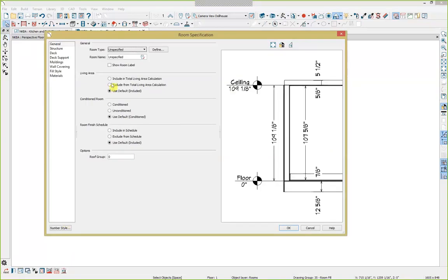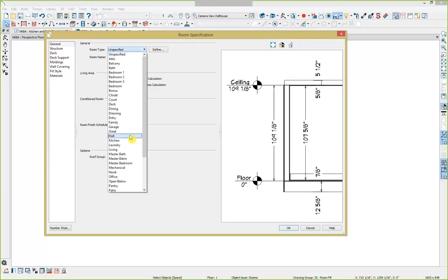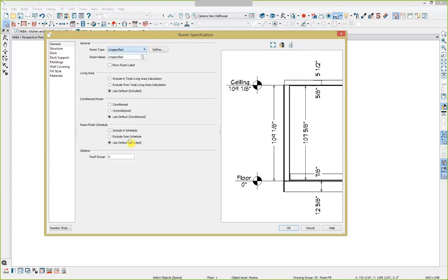And here in the middle of the screen, we open up the room specification, and you can tell the program what type of room type is going to be used here. I'm going to tell the program that this room is going to be a kitchen. What we're doing here is defining the room type. This is important because the program has other smart design features that help automate the design process based on the room type that you have selected, such as our dimensions, or more permanent dimensions, I should say, being formatted in inches, and it'll also update our flooring.